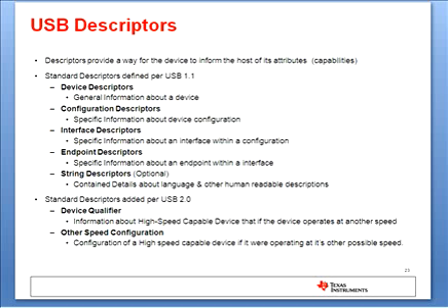USB descriptors provide a way for a device to inform the host of its attributes. USB 1.1 started with 5 descriptors, which are the device, configuration, interface, endpoint, and string descriptors. However, string descriptors are optional.